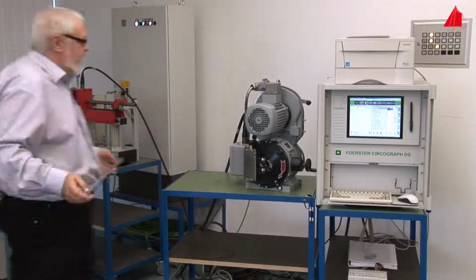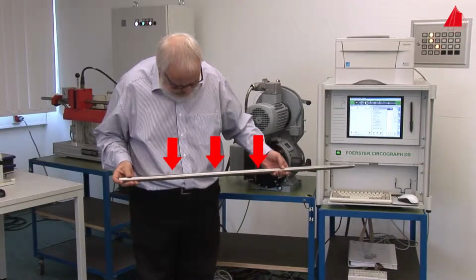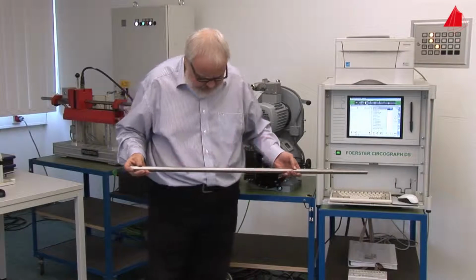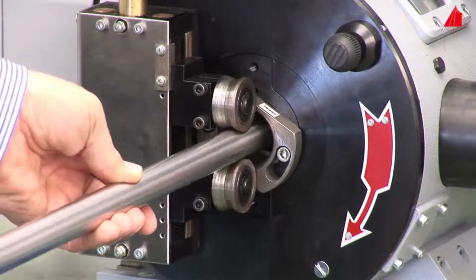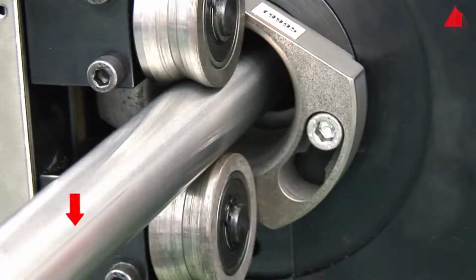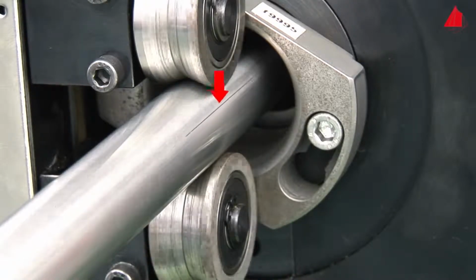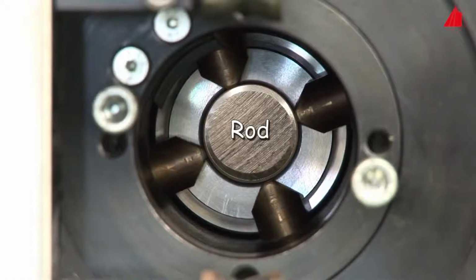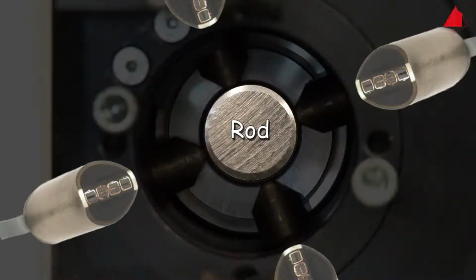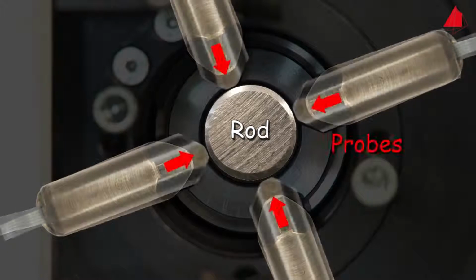This version of eddy current testing is also well suited for mechanization. 3 very fine saw cuts with varying depths have been machined into this massive cylindrical rod in longitudinal direction. The rod is again made of an austenitic steel. The materials tester pushes the test piece with constant speed into the machine, so that the saw cuts pass through the actual test area. A look into the interior of the machine shows the rod in the center. Here, the rod is not only scanned by just 1 probe, but in fact by 4. And each of the probes is equipped not only with a single coil, but with several ones.